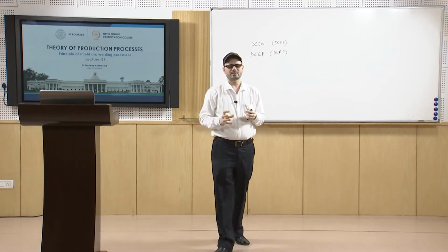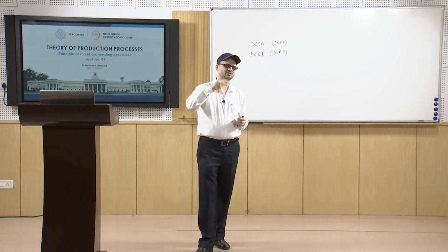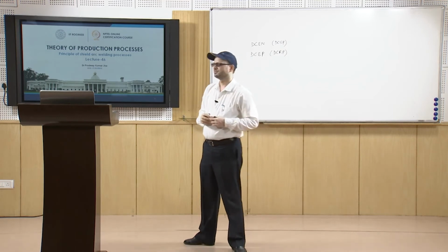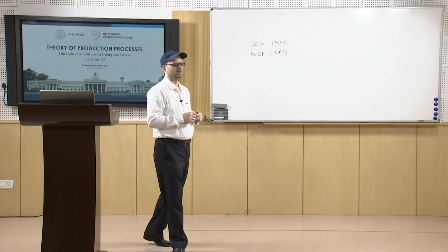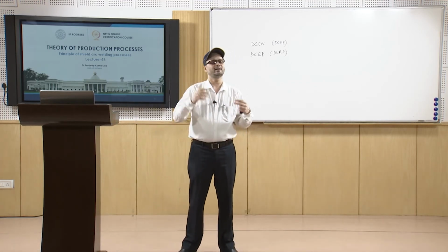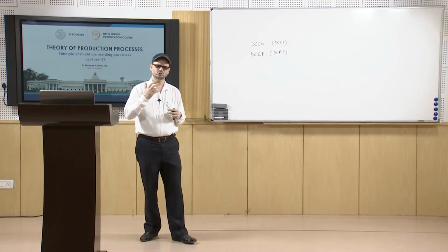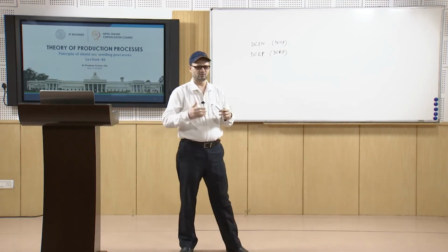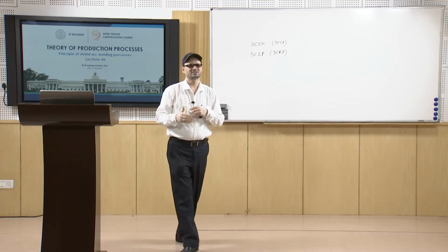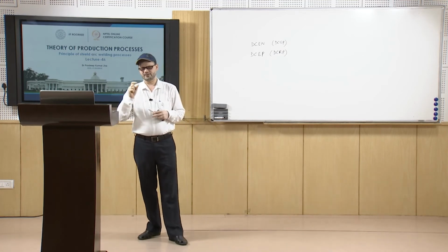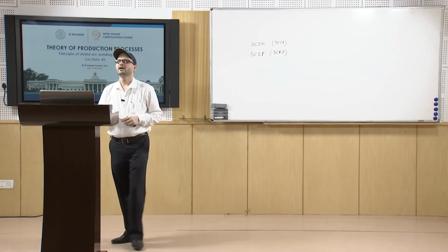That way an ionized column develops, and a large temperature is achieved, about 10,000 to 11,000 degrees Fahrenheit, close to 5,500 degrees centigrade, in that column, which is high enough to melt the material where it is hitting.